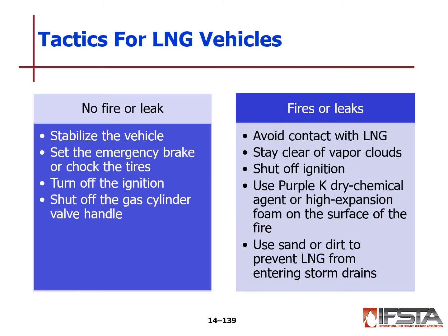For no fire or leak, stabilize the vehicle, setting the emergency brake, chock the wheels, which we're carrying now, additional wheel chocks. Turn off the ignition and shut off the gas cylinder at the shut-off valve.